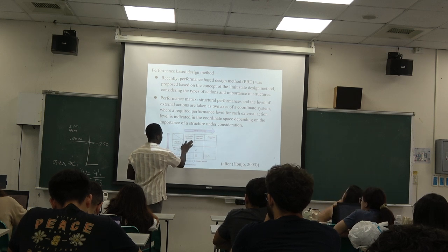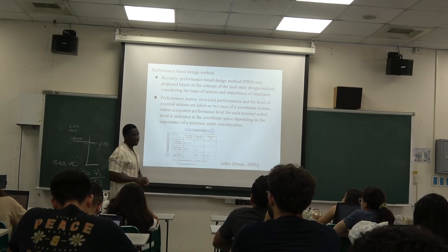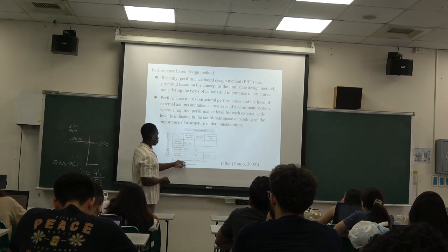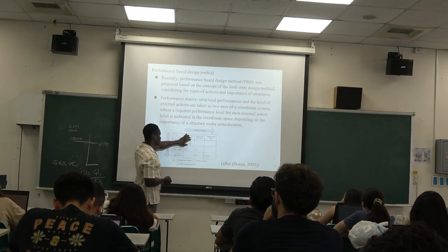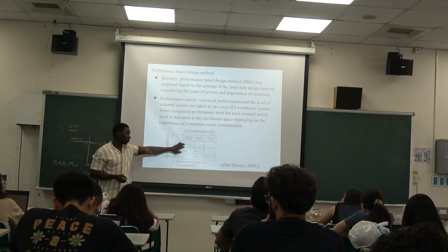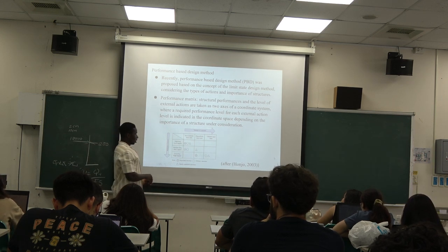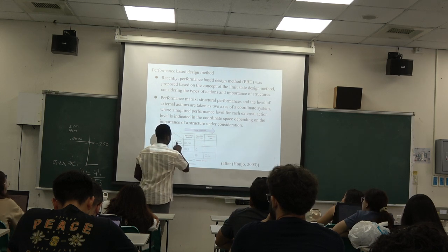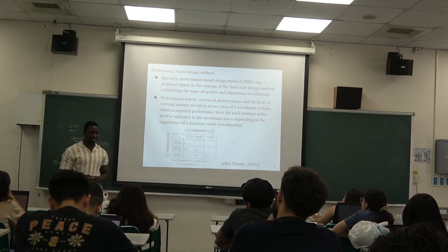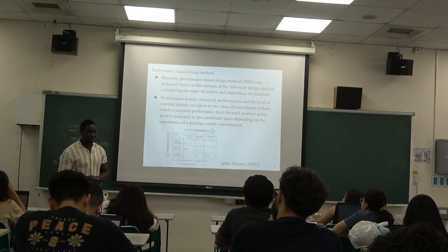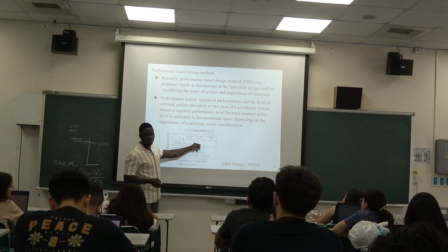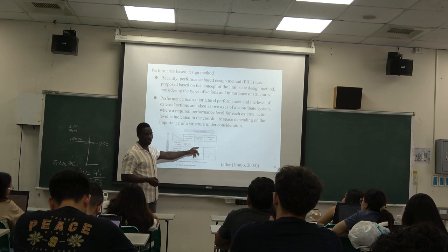So we want to make sure that our structures are all within the serviceability limit state. Okay, so the important structure, the ordinary structure, the easily repairable structure, they can all remain within this limit state in this type of condition. Because if something is high frequent and the impact is low and then your structure gets here, then something is kind of pretty wrong with your design, right? Because every time this happens, it happens very frequently. That means you have to repair.